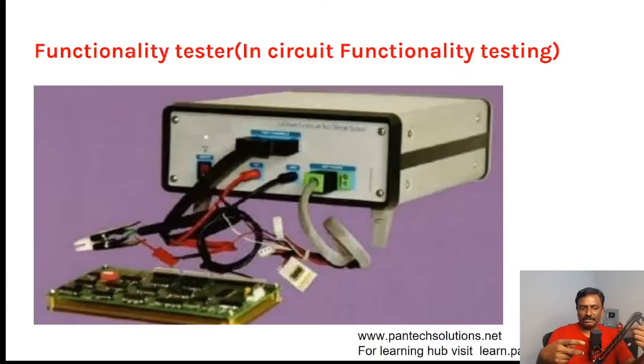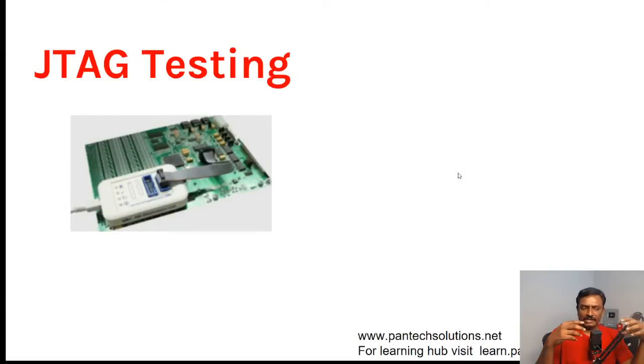There is a company called QMax Test Equipments which manufactures these devices in India, but it's quite costly, in lakhs. Then JTAG is another kind of testing. With JTAG testers, you could emulate the functionality of microcontrollers, DSP processors and FPGAs, and check whether they are working or not. So, to recap: you have JTAG testing, in-circuit functionality testing, PCB short circuit locator,